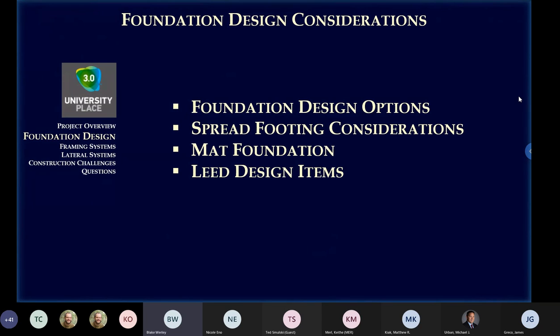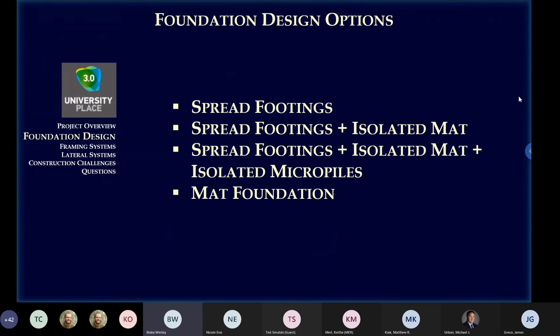It also revealed that the elevation of this bedrock varied quite a bit. So we're going to have to plan for that during construction, because where and at what elevation we reach bedrock was going to need to be dealt with then, and we were just trying to prepare for that in our design. The good news is that these site conditions were acceptable for relatively high bearing pressures and allowed for shallow foundation systems to be a viable option.